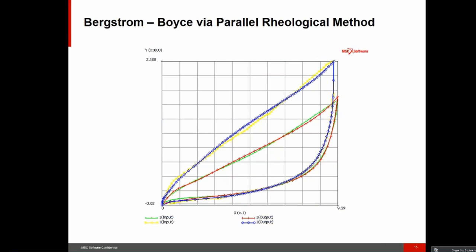Here's basically using the same model, but in this case it was a material where this curve is at a higher strain rate, this curve is at a lower strain rate, loading and unloading, and really effectively doing a Bergstrom-Boyce viscoelastic model representation using this numerical fitting technique.